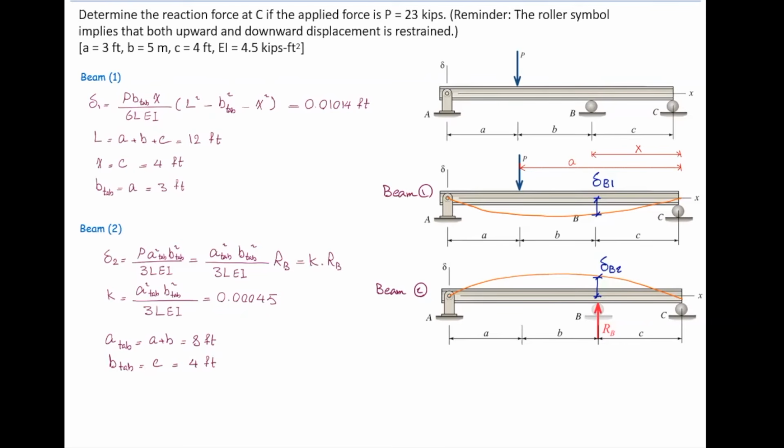All right, the last step is determining the reaction force using the compatibility of deformation. What is the compatibility of deformation in this case? How much is the total deformation of this beam at point B?